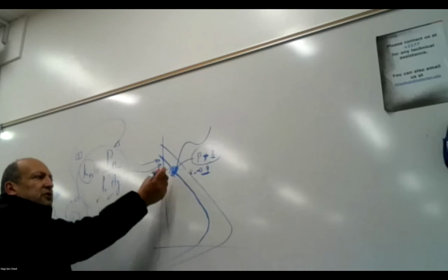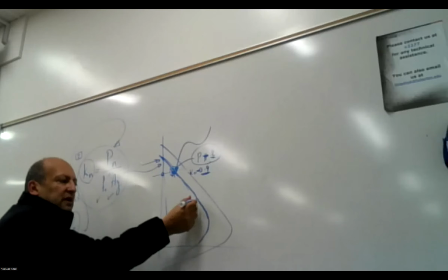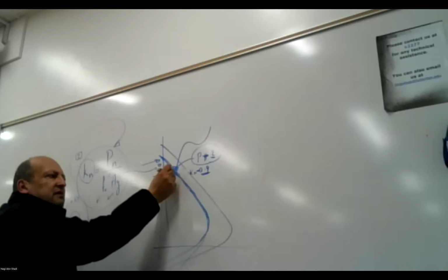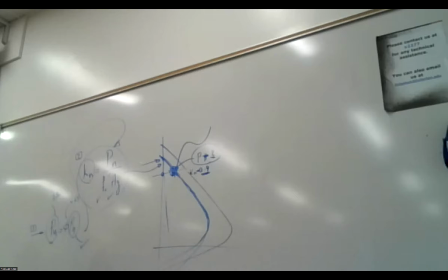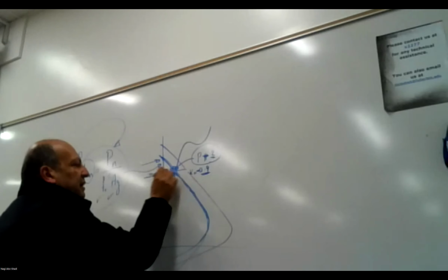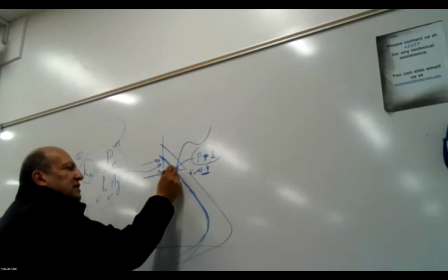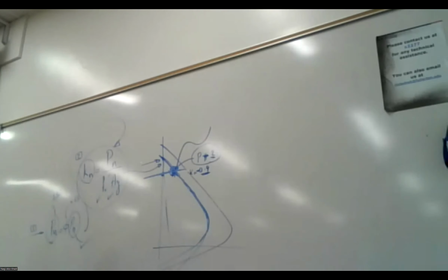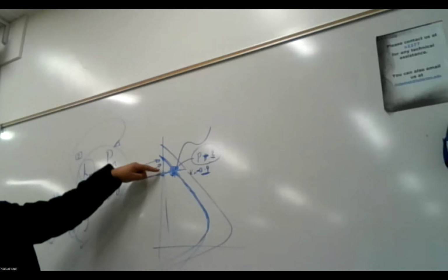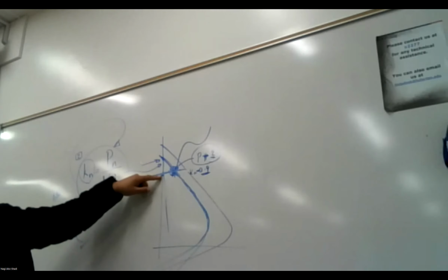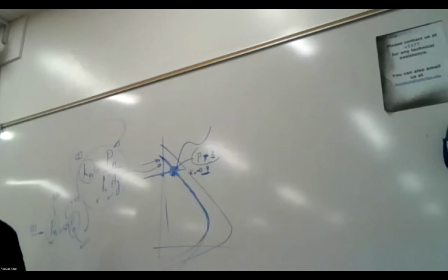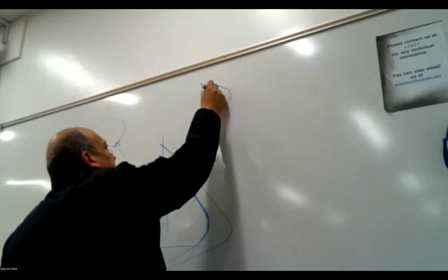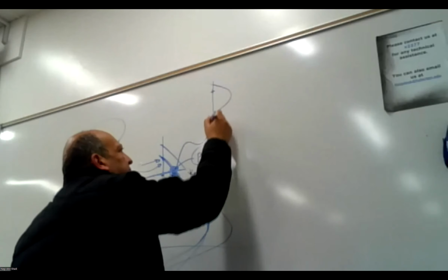And then you go in here, you pick your chart, the correct one with the same steel ratio, right? And then you put the point right here. That's it. Done. You can just do a straight line like this, or if you like, a dash line like this. Once it hits your curve, you say, okay, good, I'm lower than this, I'm good, because the maximum point was only the envelope. So this point here is going to be within the envelope. You see here, this is your envelope, right? If your point is here, it means that you're within this envelope.